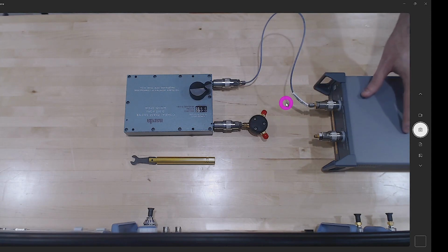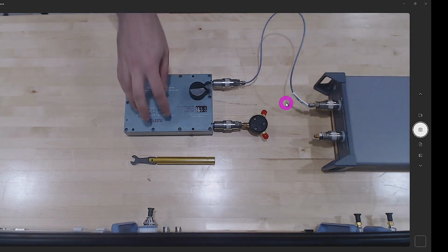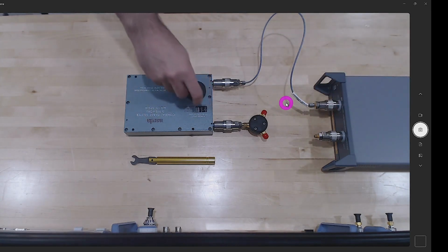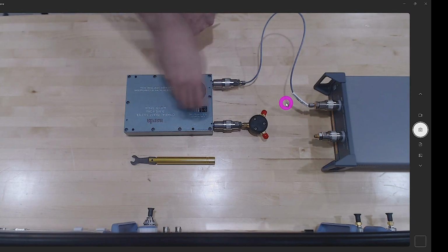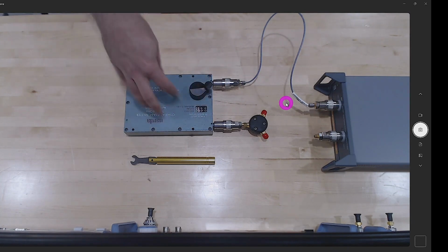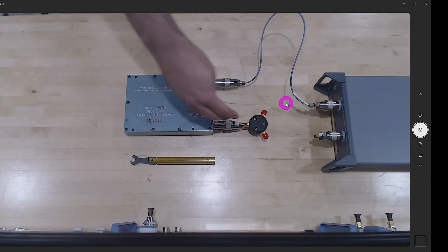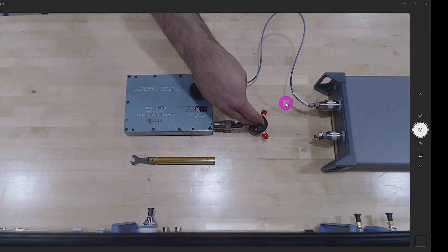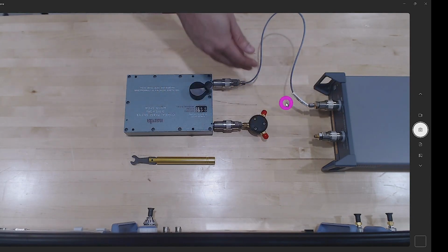So in this situation, I have port 1 connected to an adjustable phase shifter. This phase shifter is mechanical, so you can just turn this knob and it will go through the different phases, and it's nothing more than essentially a delay. On the other side, we have the termination into an open, so we have a complete reflection coming back, or a short. It doesn't really matter.